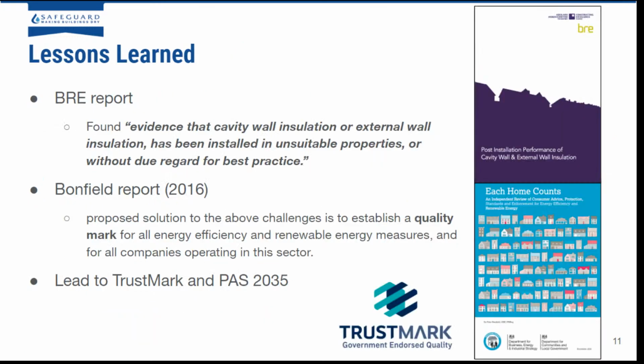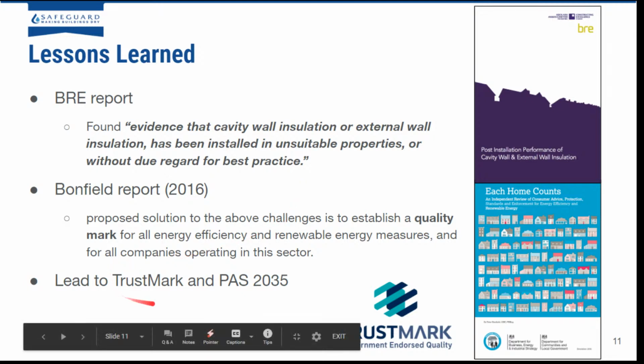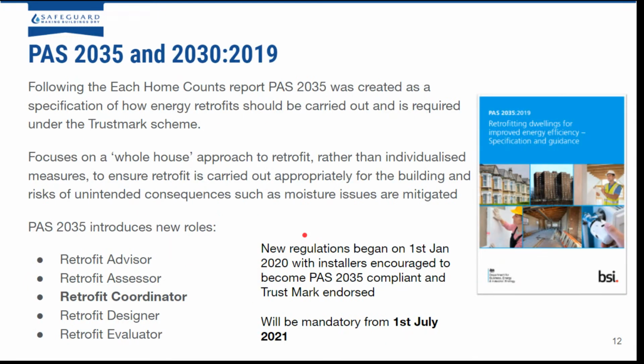So there's been lots of lessons learned from this. There was a BRE report which came out which found evidence that cavity wall insulation or external wall insulation has been installed in unsuitable properties or without due regard for best practice. And then this led on to the Each Home Counts report, or the Bonfield report. The proposed solution to the above was to establish a quality mark for all energy efficiency and renewable energy measures and for all companies operating in this sector. So this led to the establishment of something called the Trust Mark and the creation of the PAS 2035 standard.